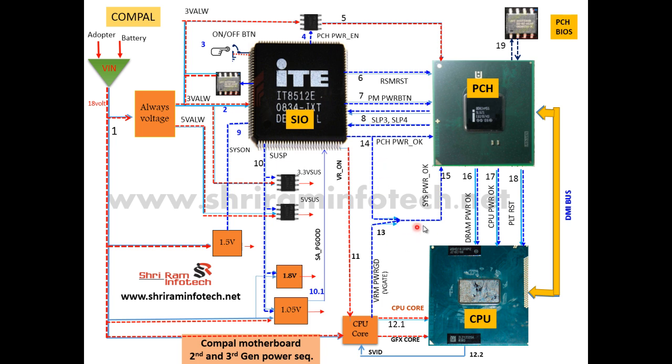And then finally it will generate the system power OK signal, then all the power planes are on, and it generates these 3 signals. So in this way this Compal motherboard power sequence works for almost all these generations. Thank you very much.